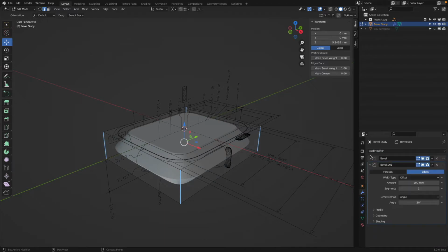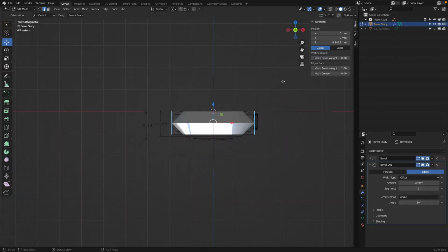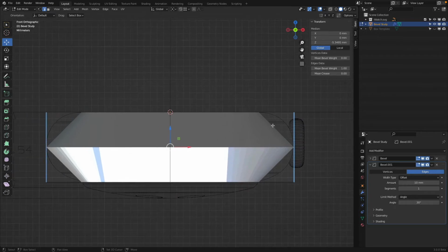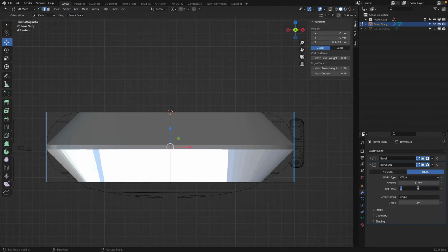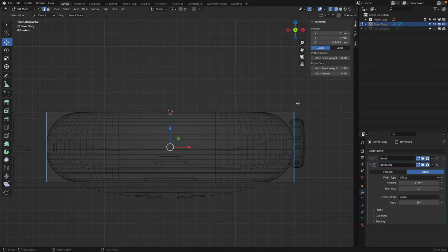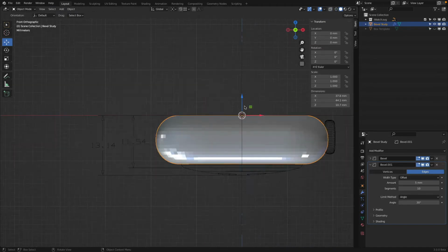So now I do another fillet feature, for example, in Fusion. And this time we say, well, round everything that has an angle. Such a devil's word. Sometimes it's angle or angel. So confusing. Why did they need to pick two words that are so similar? Anyway, rant over. Let's say 5 millimeters, 6 millimeters. You see then it fuses together, 5 millimeters. Let's go segments 10. Okay. Yeah, it doesn't look actually too bad, we could say.